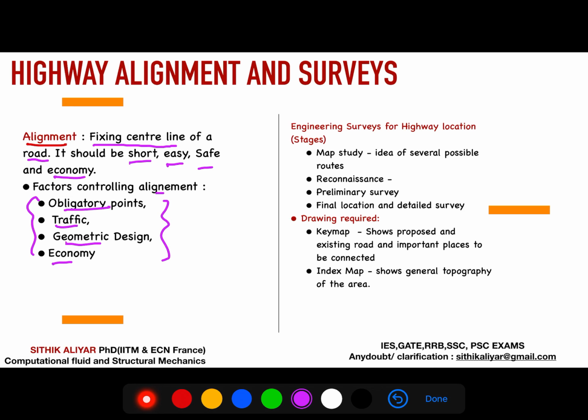And if you see the geometry design, something like side distance, super elevation, if we are facing some bridges across the road, you should consider those changes also in your alignment. Also the economic factor, obviously how much money has been allotted, whether to include yourself with 5 bridges or 6 bridges or something like that. Based on those factors also, your alignment will change.